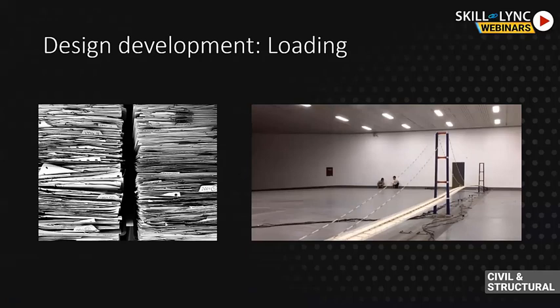Principles are quite similar in all of them, and you need to understand the principles. Sometimes for unusual and larger structures, you do testing, such as wind tunnel tests for your wind loading. This is done for cases where your codes don't really cover the situation, or you want an extra level of reliability, because codes are drafted for general structures and your structure may be quite specific.